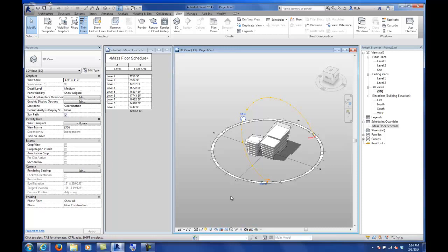So the idea about this peeling away effect, that might be where you would model another straight wall that shows that peeling effect, how far you want to go in that mass, and then you could apply your actual wall component to it and still leave the rest of the building there. But you could also apply it to this wall or any of those sides, or even the floor plates could also be extracted that way as well. As long as it's a mass, it's an underlying element that any roof element, any floor element, and any wall element can eventually be applied to. So yeah, you could cloak it based on that.